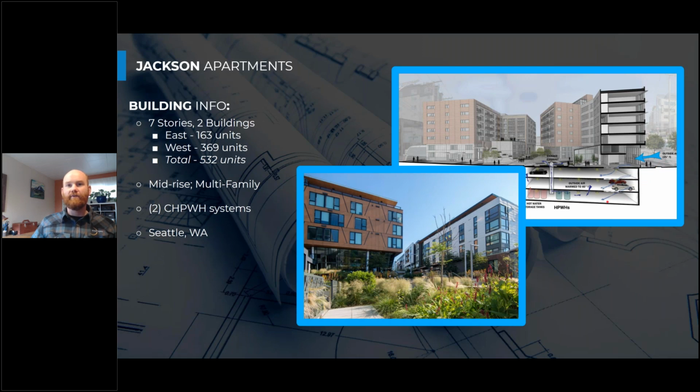So there's garage exhaust fans running continuously, and those are pulling outside air, around 23, 25 degrees on our design day, into the garage and pulling it down through multiple stories of our garage. In Jackson Apartments, we go down about 2 stories, and then that air is pulled into the mechanical room by the heat pump water heaters.